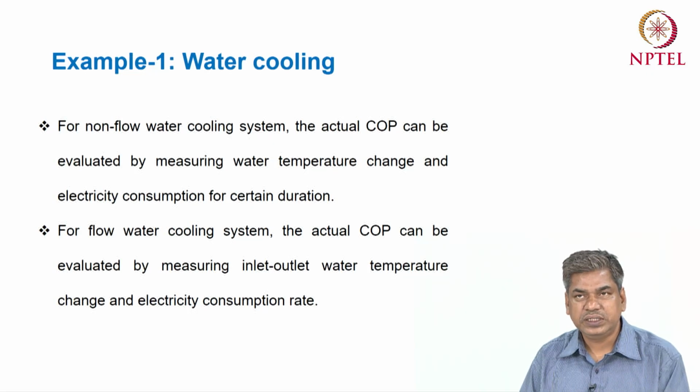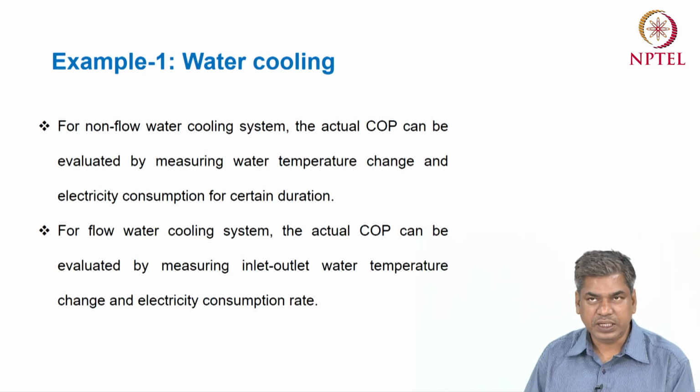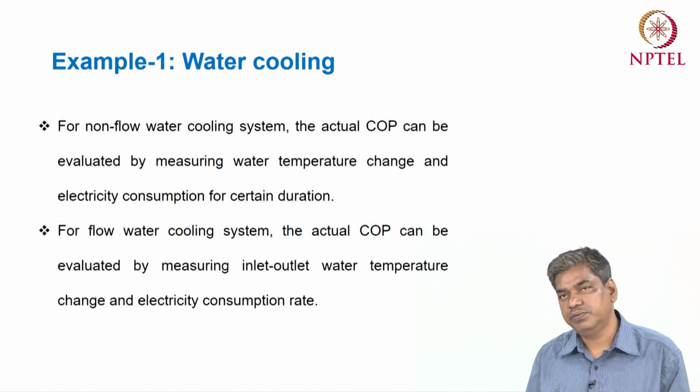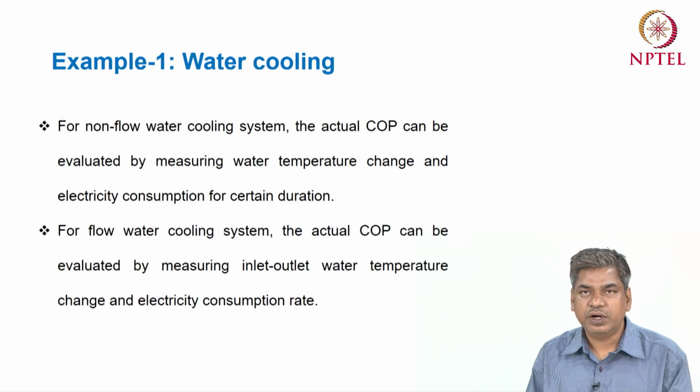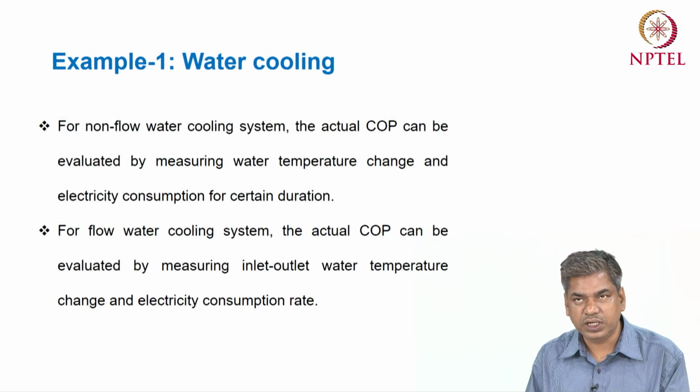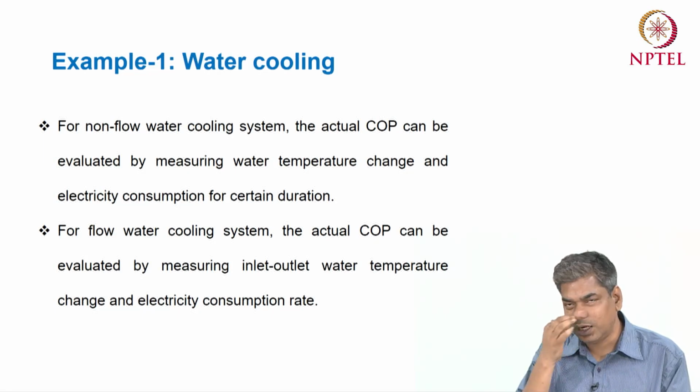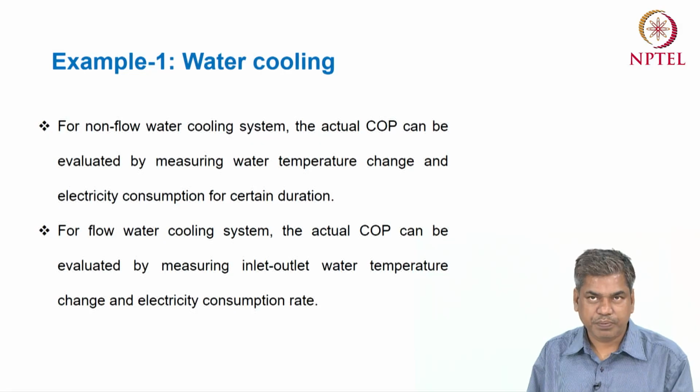After some time, you again measure the water temperature and the electricity reading. Within that time we can determine the electricity consumption and the water temperature change. If you know the volume of the water and its heat capacity, we can calculate the refrigeration capacity within that time.